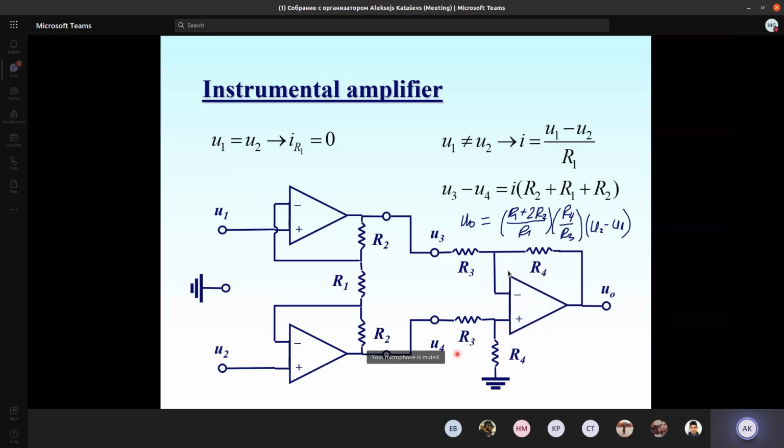Very often, what is important for the amplifier to work correctly is actually not so important whether the two R2 resistors are exactly equal, because we see that we don't use the equality of the R2 of these both resistors anywhere here in the calculation. So they may be a little bit different. In any case, the voltage generated here will be just R1 plus R2 plus R, all these three resistors added together. So it's not necessary to make this R2 ideally equal.